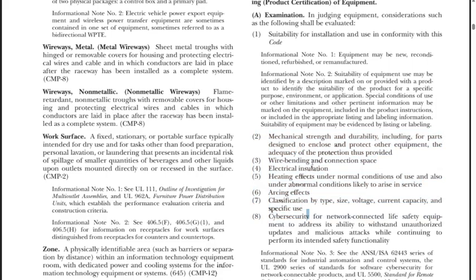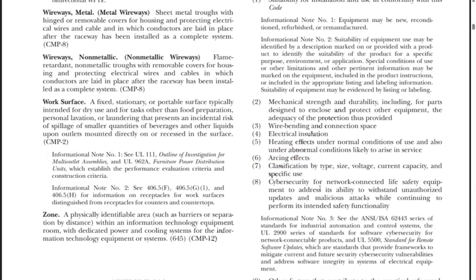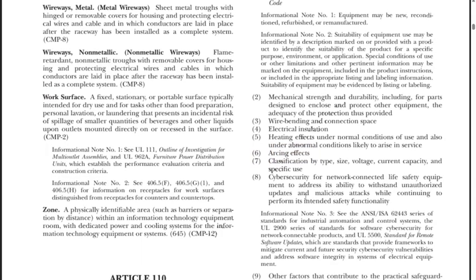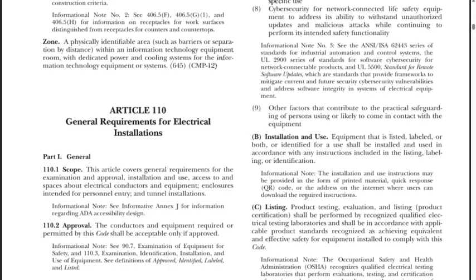Mechanical strength and durability, wire bending and connection space, electrical insulation, arcing effects, right? We have arc fault protection devices for that. They should be listed and tested for all that as they go and get installed, right? Sold and installed.